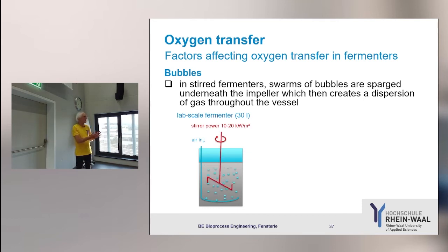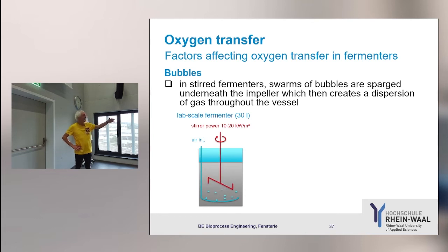Of course, you have heated it to a constant temperature so that the measurement makes sense. Therefore you have this invisible heating device around. The other reactors which were standing next to you on the bench heat differently. They heat with water, so you can see directly what's happening. However, they have different stirrers. They are for high viscosity fluids, so the transfer rates there are different. We want to use them also for solids, and therefore stirring is completely different.